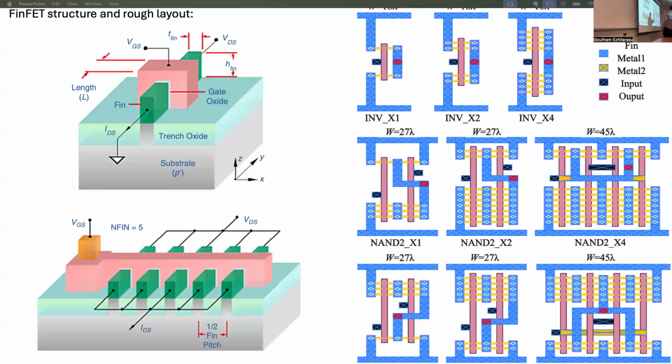There will be a via here that goes to this metal line. And from here, there's a contact that then goes to the source in this case. And then similarly, you have another metal that takes it out from here, brings it here, and then goes down again, and so on, right? This is just a top view. It's a 2-dimensional view, but this actual structure is 3-dimensional. There are basically multiple levels, and to go from one level to another, you have vias or contacts, right?